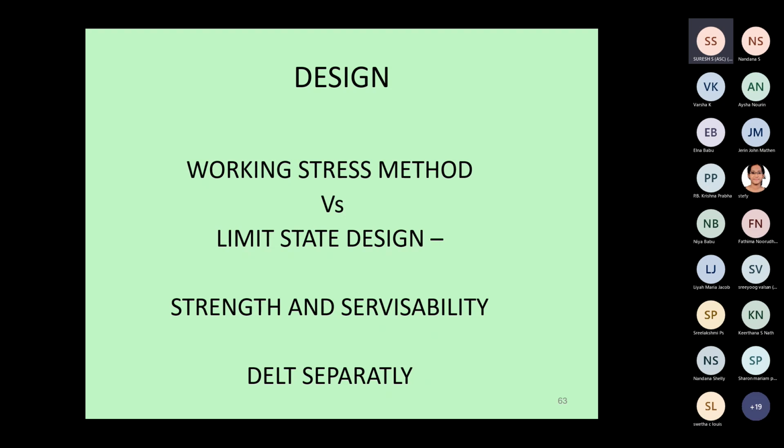That is just like we discussed, Fe 250 steel or Fe 500 steel, we apply a part of the factor of safety, called partial safety factor, on the basic material strength of 500 Newton per mm square, and the other part of the factor of safety is applied on the loads, or the bending moments or the load effects.